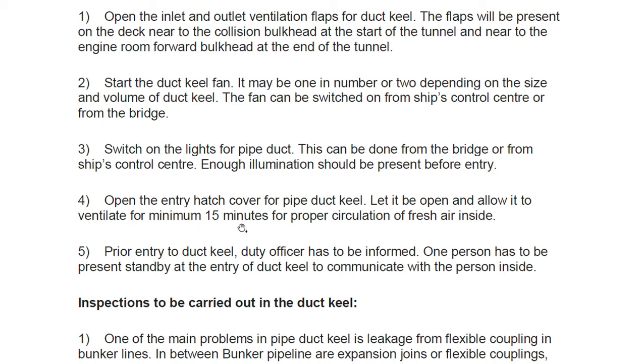Open the entry hatch cover of the pipe duct keel. Let it be open and allow it to ventilate for a minimum of 15 minutes for proper circulation of fresh air inside. So we open the entry hatch cover. There is an entry because we cannot enter from this flap. So there is an entry hatch cover, and we need to open that, because that has also been closed for a long time. So we keep it open for 15 minutes for proper circulation of fresh air inside.